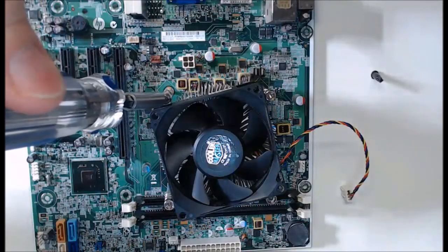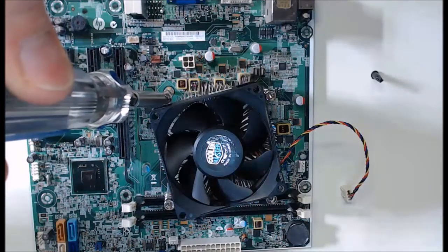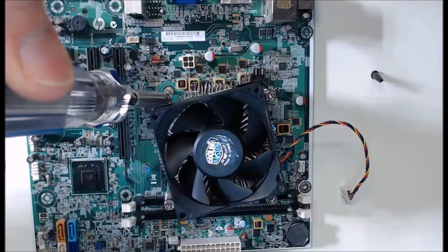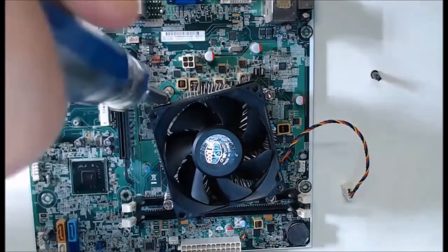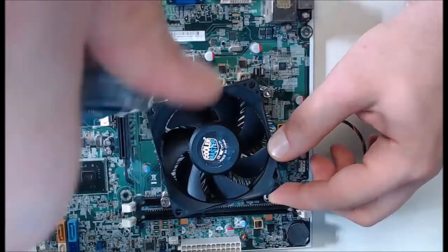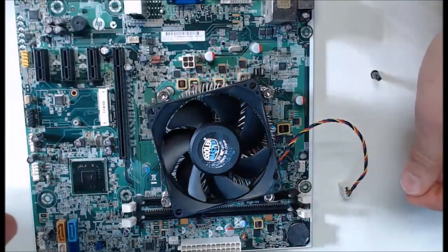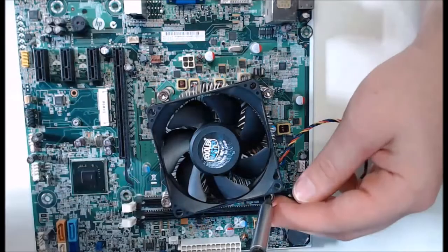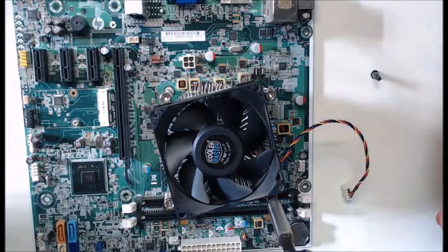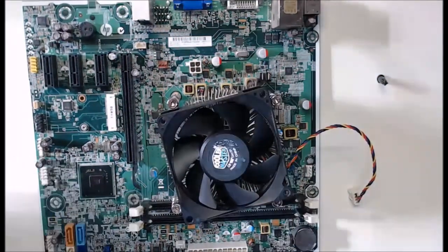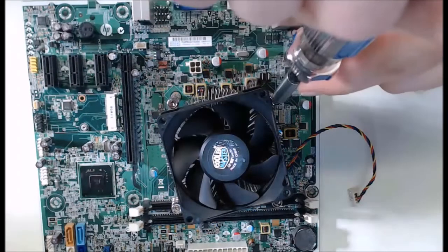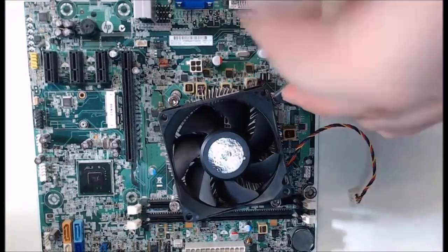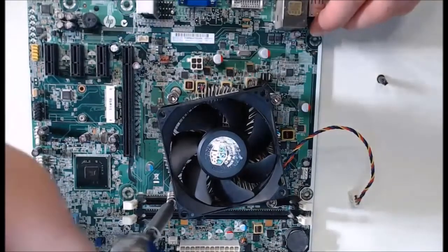As I mentioned, we'll go diagonally across to the other corner. Now we can continue our last 2 screws. Now that all 4 screws are locked in, the heatsink will not be able to move or shift at all. Having a tight flush fitting will also allow the CPU to better stay cool.